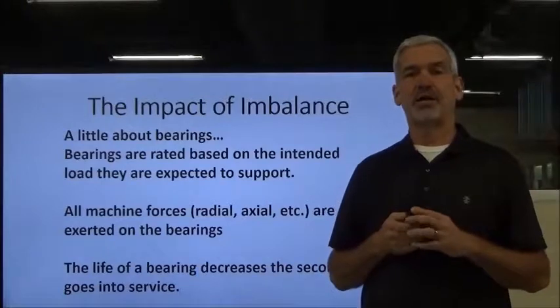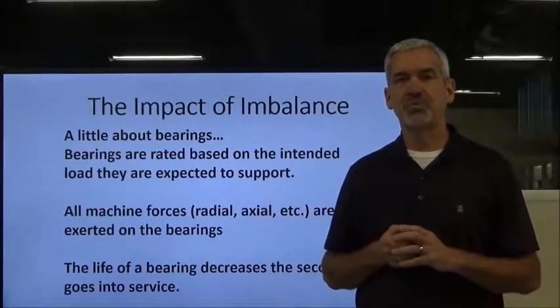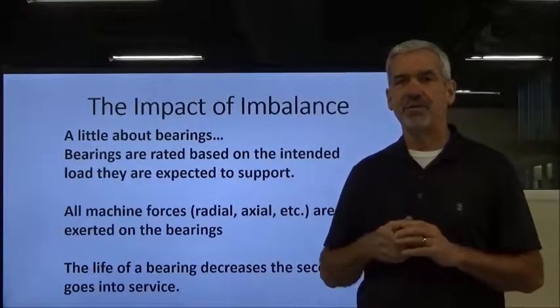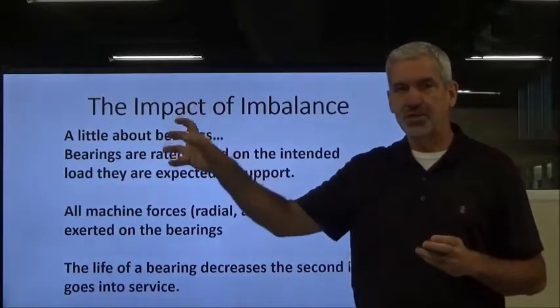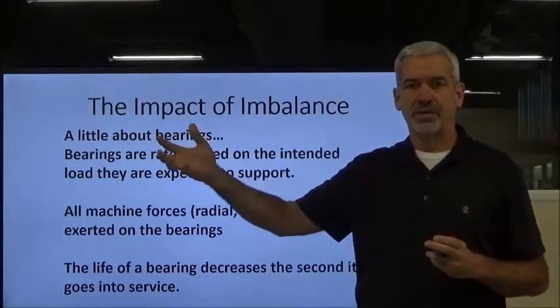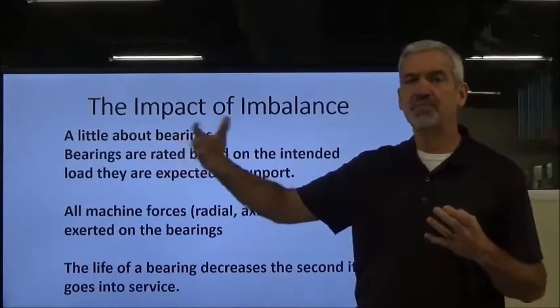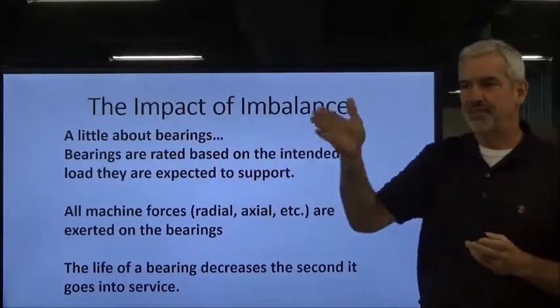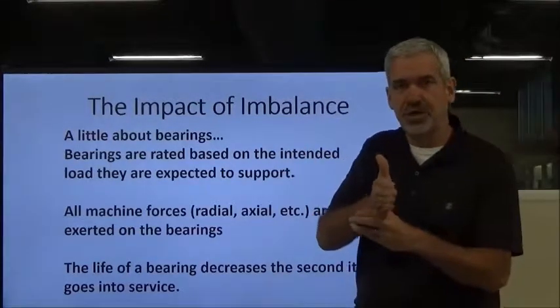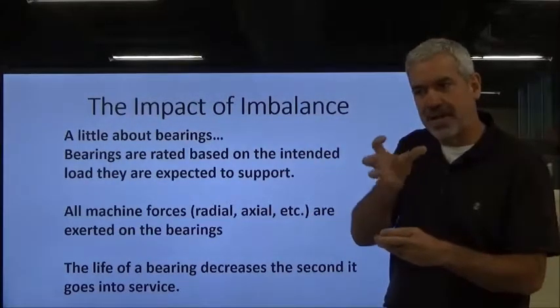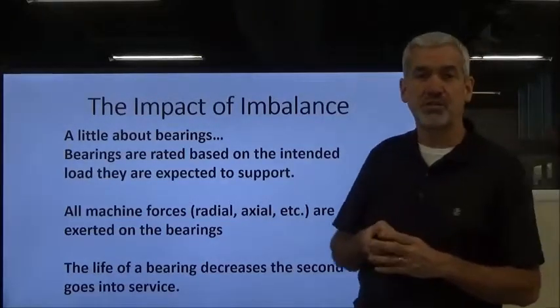A lot of motor manufacturers will recommend that if you have a warehouse that has several spare motors in there, that you turn those shafts of the motor 90 degrees every month or 2 months or something like that, and it keeps them from pounding notches in the same place as they would do if the shaft was not rotated. So they have you rotate. Also kind of keeps the grease fluid as well.